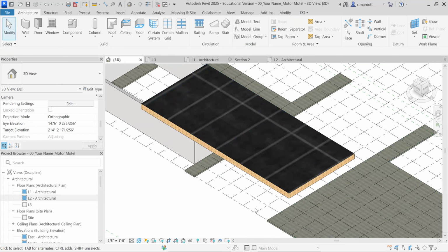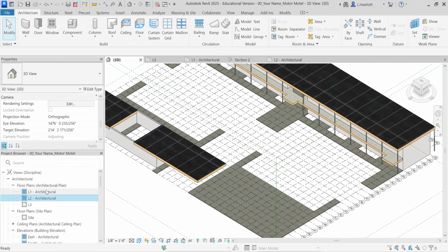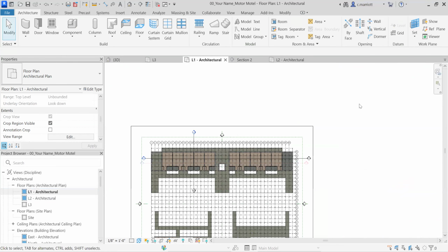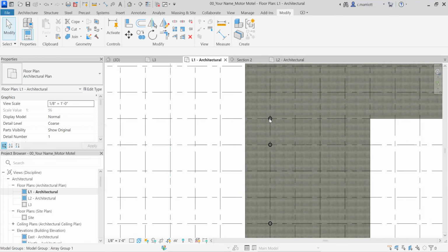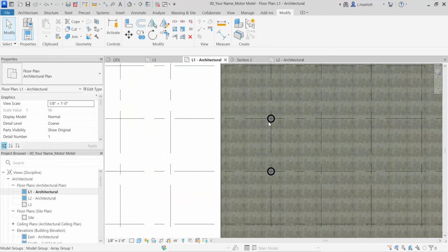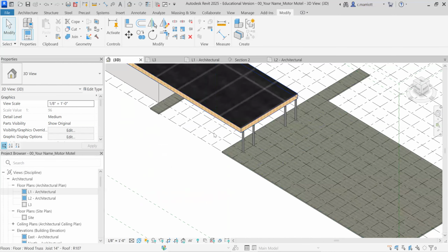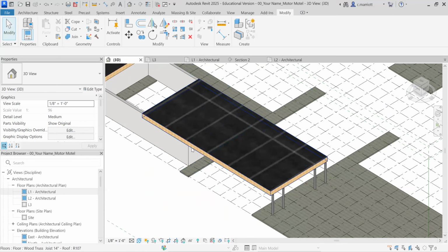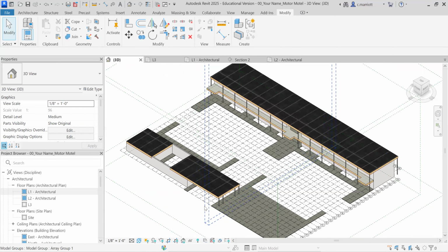So what I'm going to do is add some columns underneath it, like I had done previously over here for these exterior walkways. So I will do that from level 1. Okay, so I added some columns and I actually made them bigger. The defaults were 6 and 12-inch diameters. This one is an 8-inch diameter, just because it's a pretty lengthy span from here to here, and hey, this roof assembly might need to be deeper. It might actually include some steel, but we won't get into that at the moment.